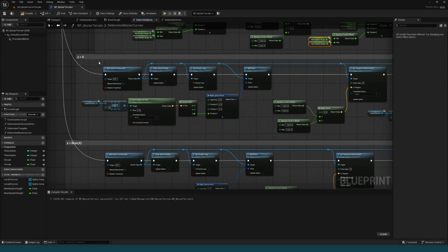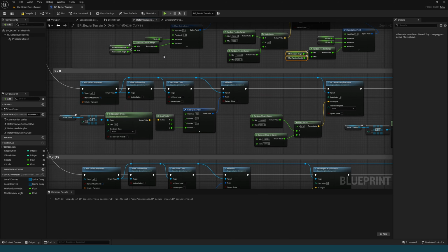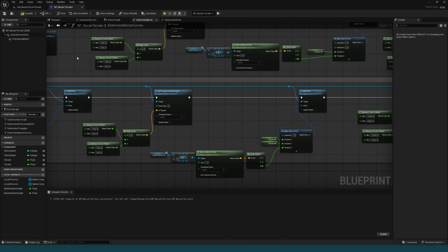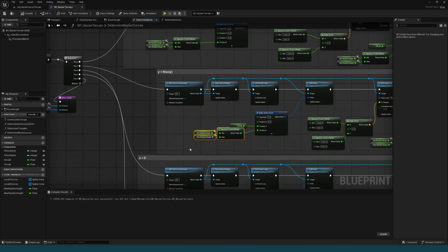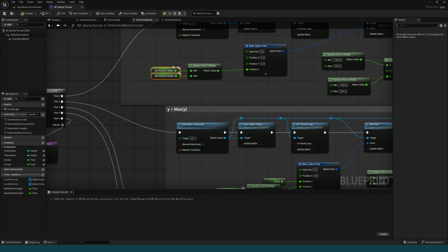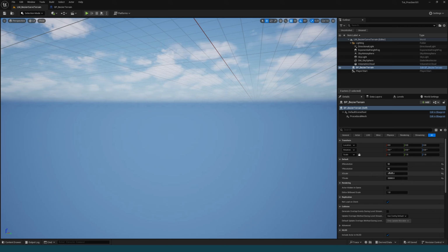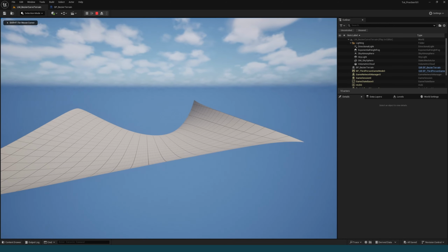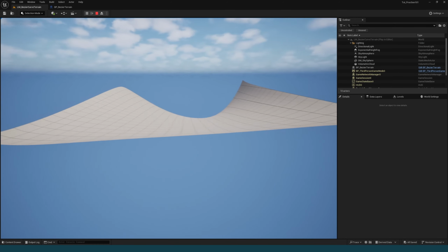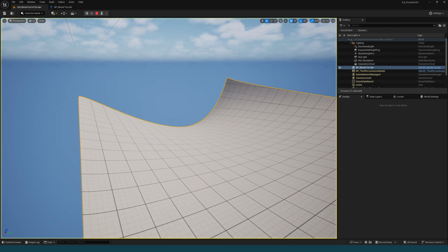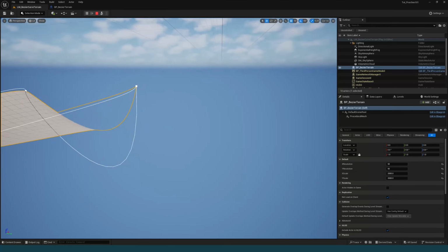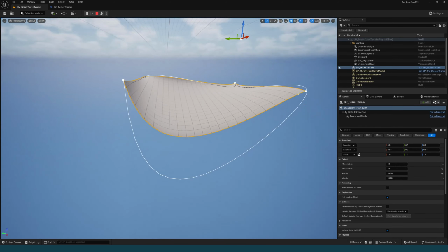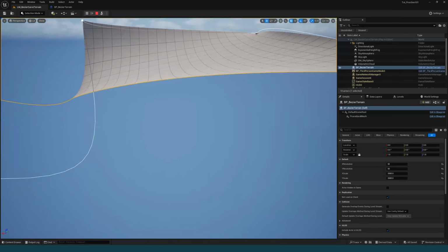Then our heights for the two X curves should not need these random heights since we're grabbing our height values from our Y curve data. So let's get more control over these random heights. Go back to our Bezier train. Let's set its scale back to 2000. Hit play. There we go. So now we're getting a bit more dynamicness in the overall changing of the heights in our curve. And here you can see we're getting quite different curves based on our large tangent changes as well.